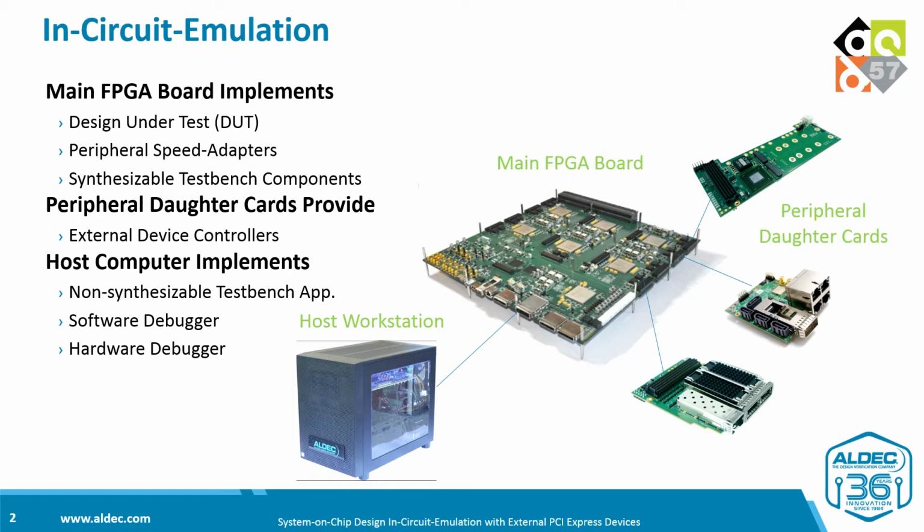Since the emulated DUT clocks have lower frequency than designed for the target chip, and the peripheral devices usually work at target speeds, it's required to connect additional buffering modules between the DUT and peripheral, and these additional blocks are called speed adapters. FPGA Fabric is also the good place to put such speed adapters.